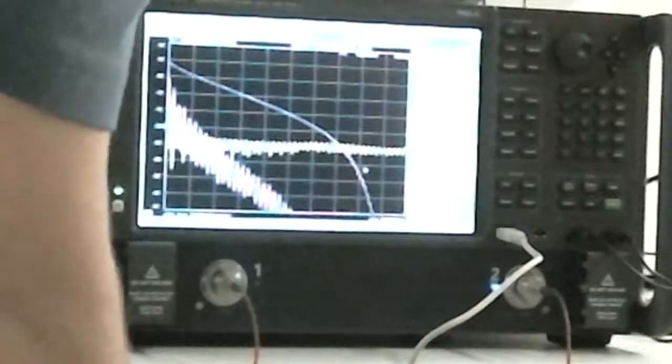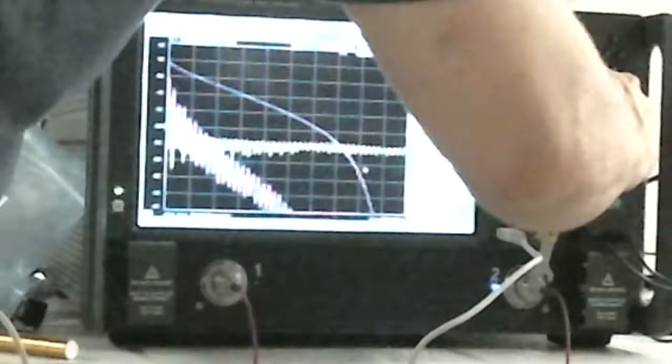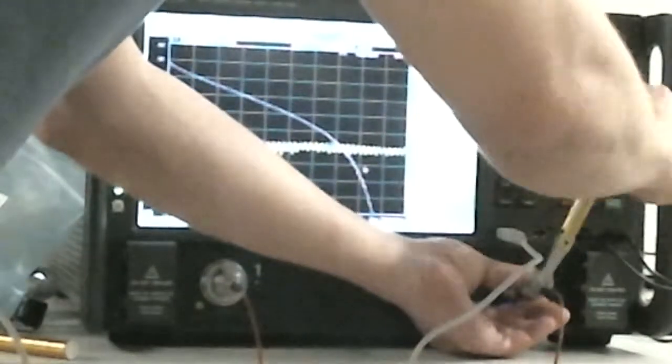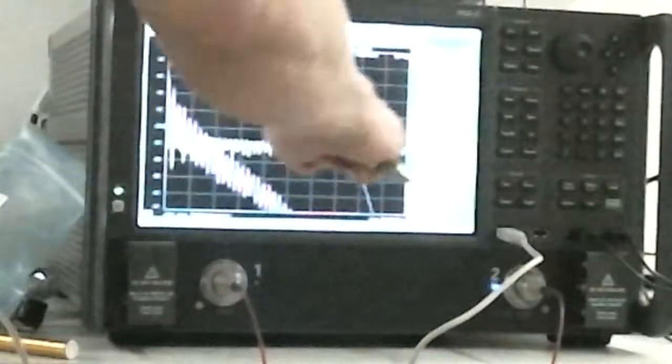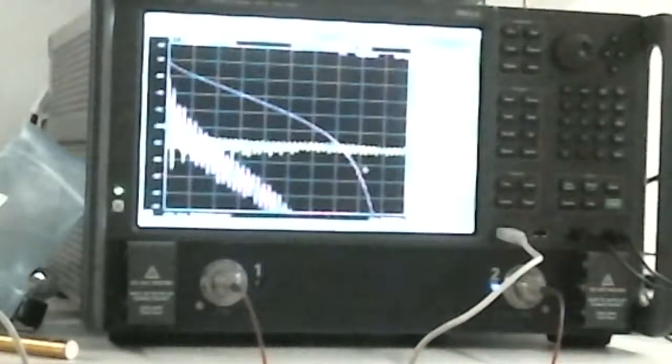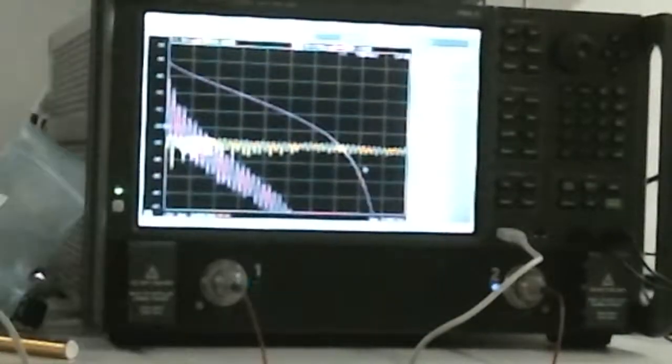Calibration. Now, I can tighten it to make sure that we're getting the right... Yeah, this cable's got not a very good match. I can see that right away. There's a different impedance level, or the return loss of the cables, yeah, it's not very good. So you can see you're getting roughly about 2.5 dB of insertion, but you're getting a lot of ripple. That means that there's a standing wave kind of going on. It could be in the connector or something like that.